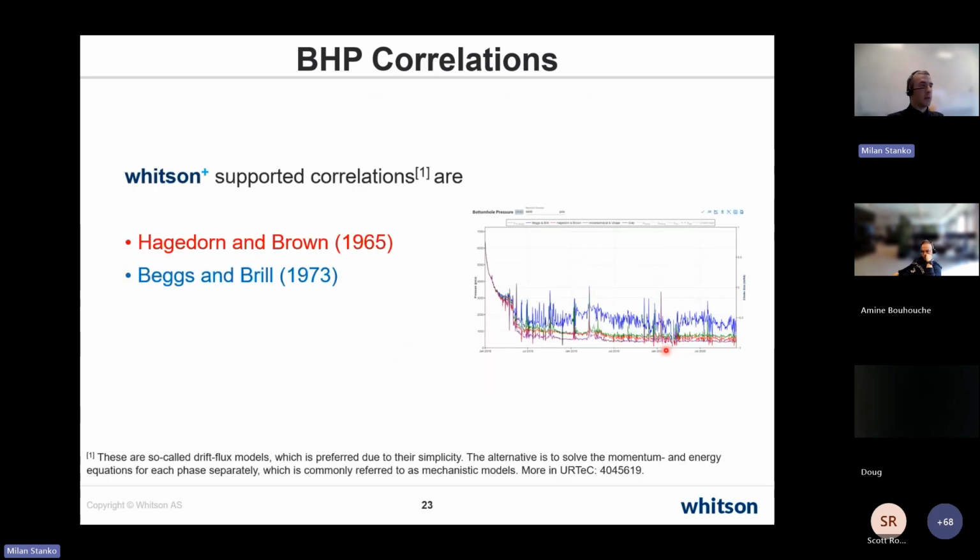And the other thing is that they are using data that was usually gathered in the lab. So in the lab, they run tests usually in small pipe sizes, and then from there they generate some sort of trend correlation, sometimes quite smart. There are a lot of parameters you have to change, so they find a way to put all of those parameters into one main parameter, usually dimensionless, and then do the correlation development with that.